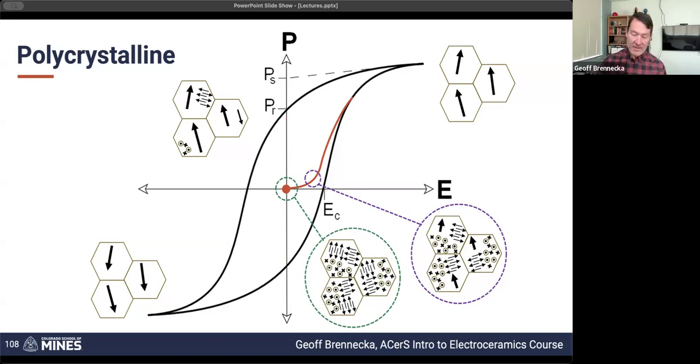So in this case, even though each individual unit cell is non-centrosymmetric, it's polar, it's piezoelectric, by the time we add up the contributions from all of those domains and all of those grains, it equals out to zero because of the equivalent macroscopic infinity M symmetry. But once we have landed in one of these remnant polarization states, now we no longer have infinity M symmetry.